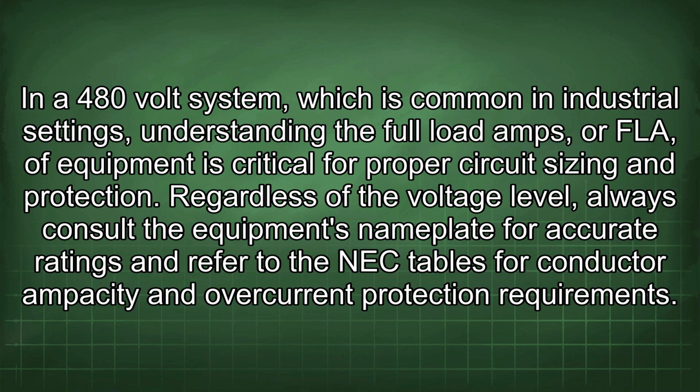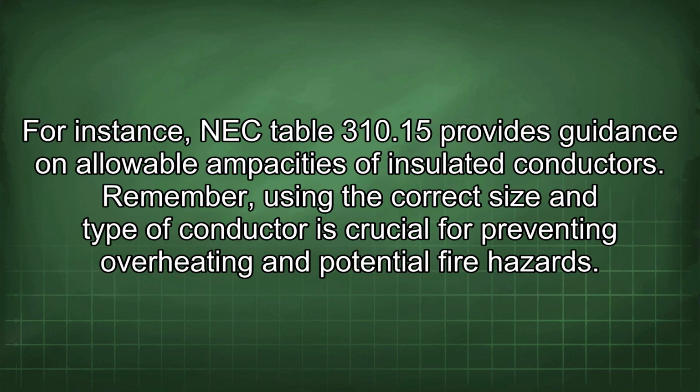Regardless of the voltage level, always consult the equipment's nameplate for accurate ratings and refer to the NEC tables for conductor ampacity and overcurrent protection requirements. For instance, NEC Table 310.15 provides guidance on allowable ampacities of insulated conductors. Remember, using the correct size and type of conductor is crucial for preventing overheating and potential fire hazards.